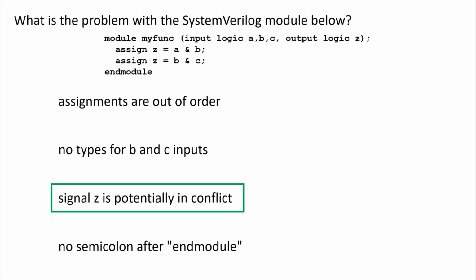It doesn't support Z and X, which to me seems like that would break the Verilog standard. I mean, that shouldn't even be allowed. But yet they do it. Somehow they get away with it, and people still use Verilator. I don't like how Verilator doesn't support the X and the Z. It's not a complete implementation of Verilog, at least in my view. There's probably some rationale behind that I'm just not familiar with.